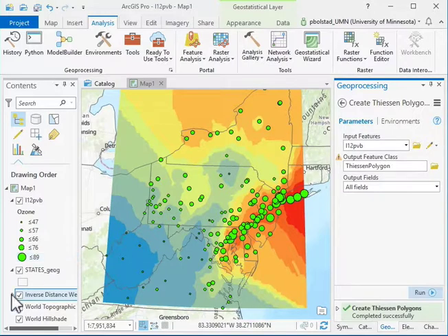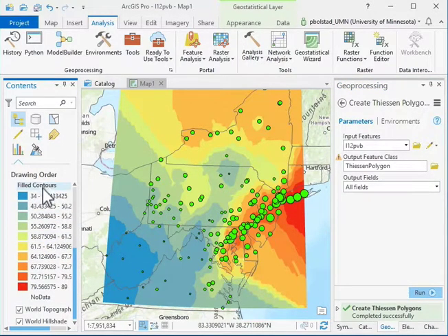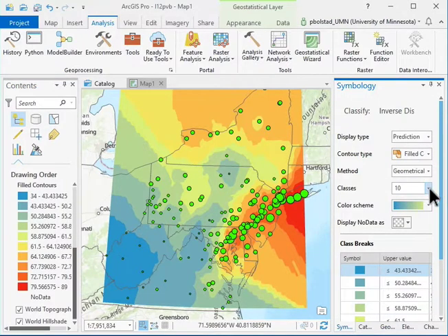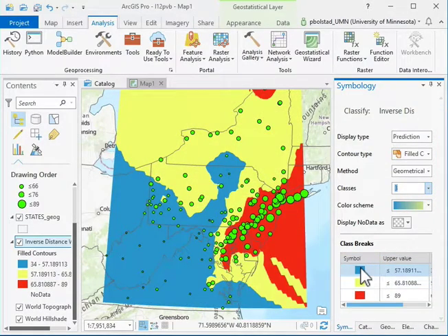And so I have this inverse distance weighted surface here, and I can then color this as I did the others. So if I look at the symbology for the inverse distance weighted, I can go then to the same 3 classes with the same 3 thresholds that I picked before. Right, so I can set this value here at 54 and this value at 70 and get a surface then that shows where there's high ozone, intermediate ozone, and then ozone levels I don't have to worry about.